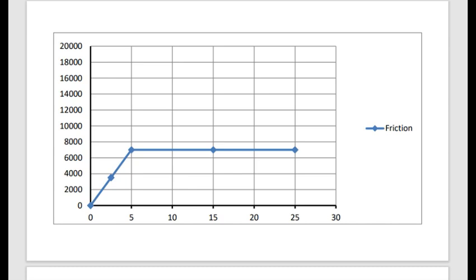As you know, there are two components for the load carried by the pile or by the soil. What are these two components? We said the friction and the end bearing. Imagine that this curve shows the frictional load.